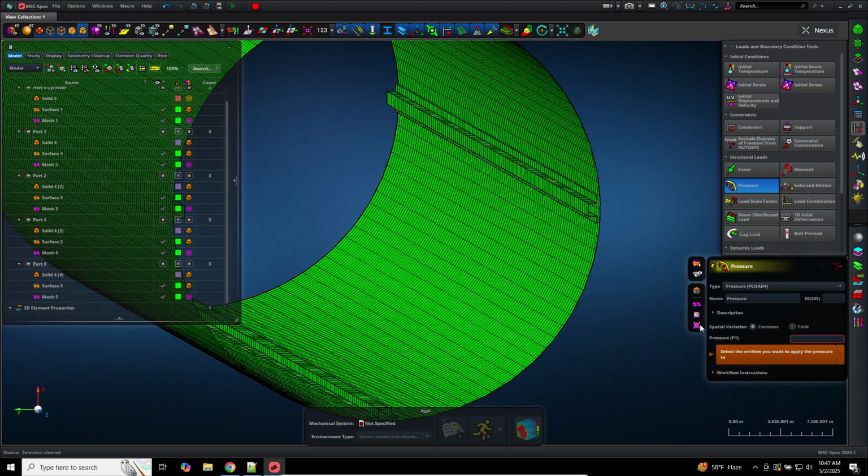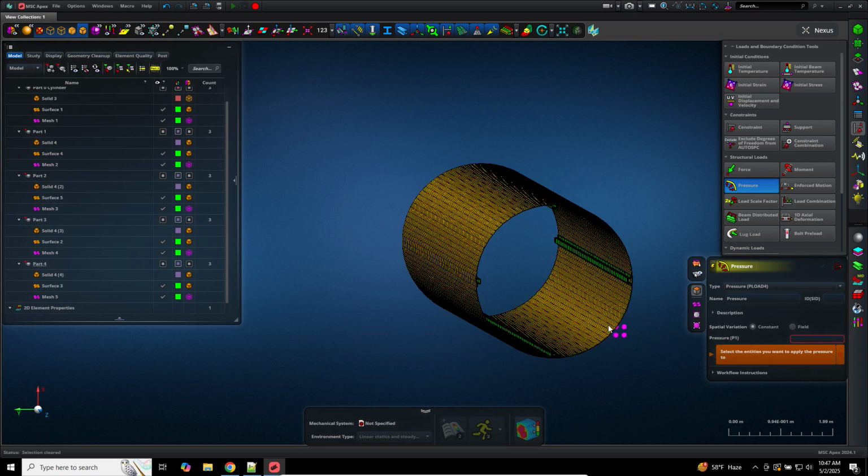Here in this vertical option, you have the option of selecting specific objects to select. Here I say, you know what? Ignore all the elements and the nodes. Just focus on faces for now. So here I'm only selecting the cylindrical surface, if you will.